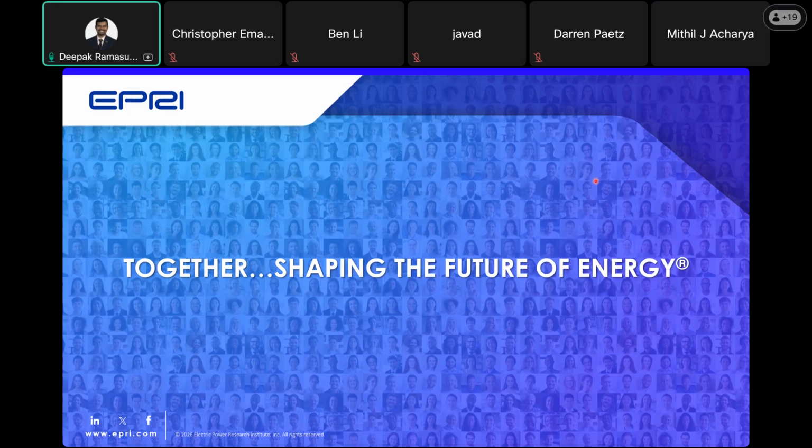Yeah, so there are ways and tests that can be used to evaluate whether it is prioritizing voltage or frequency control, or active power or reactive power control. These tests are both in time domain and in frequency domain. The frequency domain tests may sometimes give a more comprehensive picture of how these resources are behaving, because they give insight into different disturbance frequencies, which will cover both subtransient and transient.